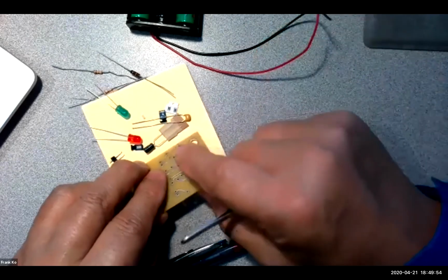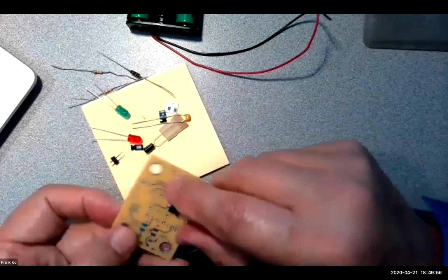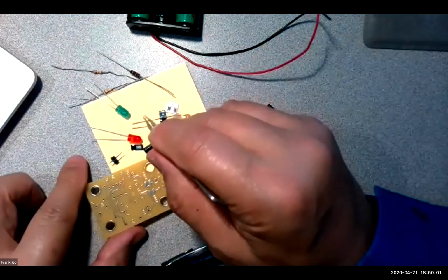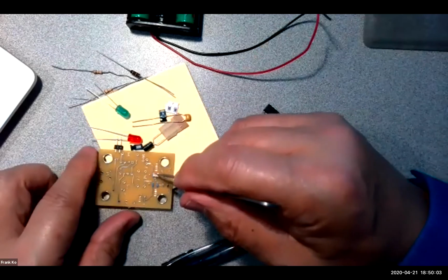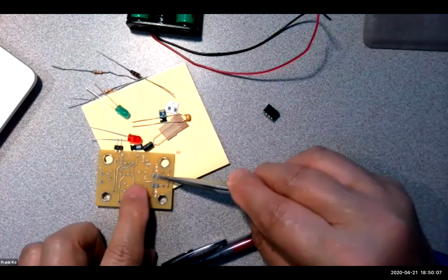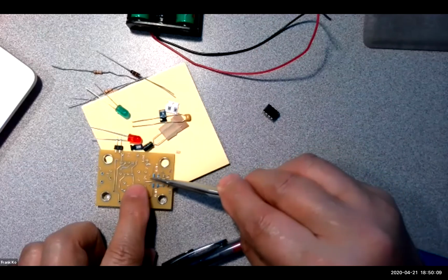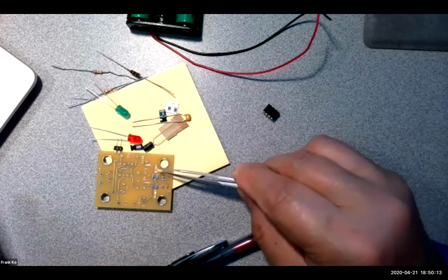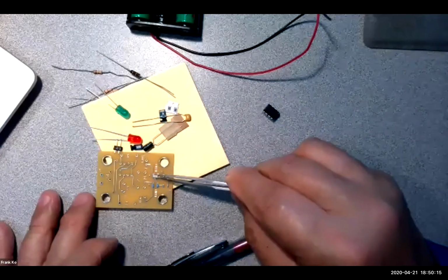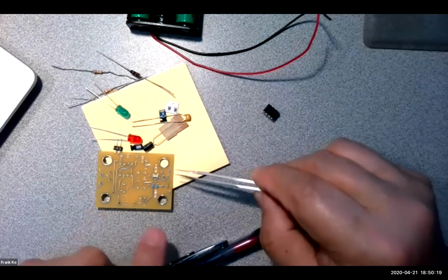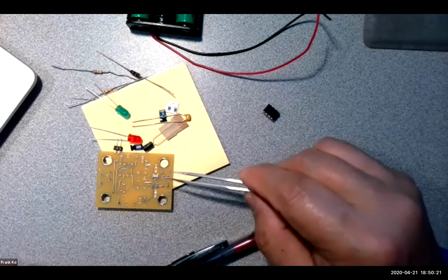In the instance of the surface mount, you will be using the tip. So if I grab my surface mount component and put it on the pads, as I've said before, you will already have put a tiny bit of solder on the pad here and here. Then after that's cooled off, make sure that the LED is in the proper orientation, negative to negative, positive to positive.